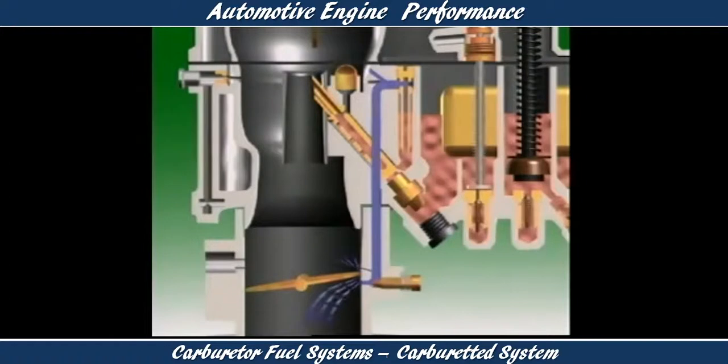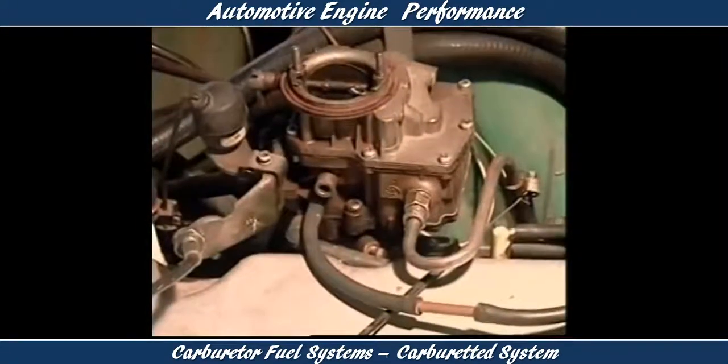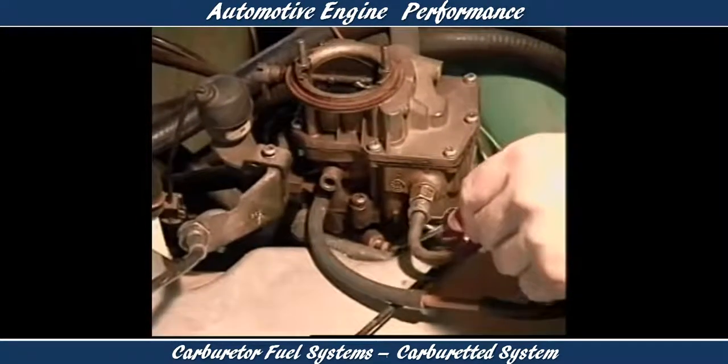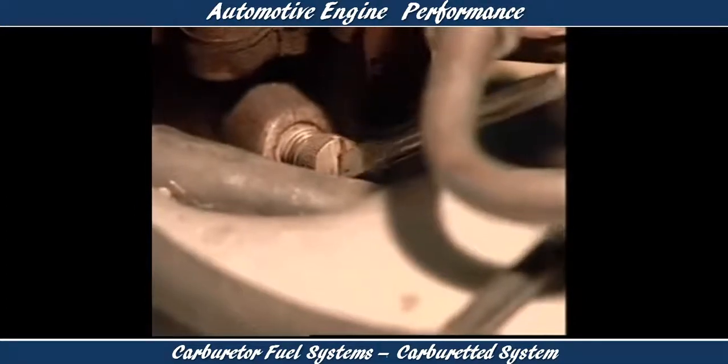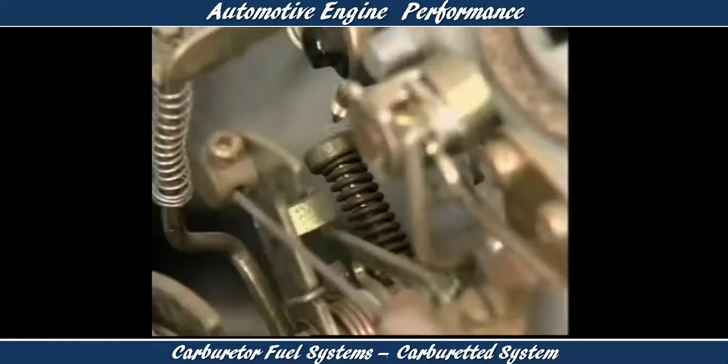Fuel flows from the float bowl through the idle passages and into the carburetor below the throttle valve at the idle port. The air bleed lets air enter the fuel on its way from the float bowl. This helps aerate the fuel before it reaches the idle port. Engine idle speed is set by two different adjustments. The amount of fuel is adjusted by the mixture adjustment screw at the idle port. The amount of air is adjusted by changing the throttle stop screw.